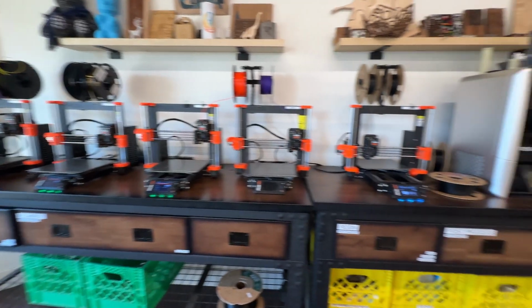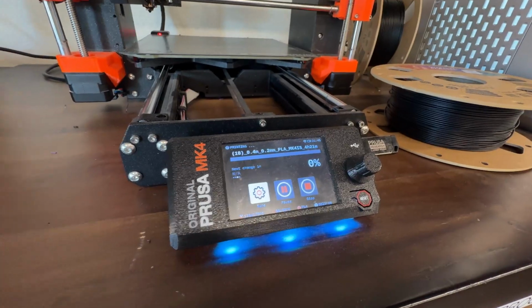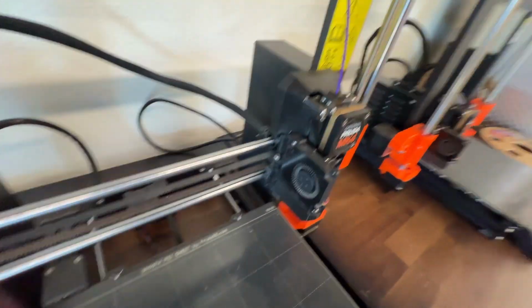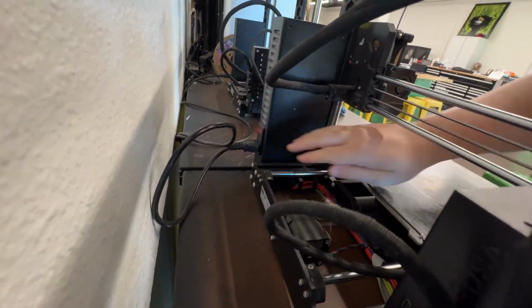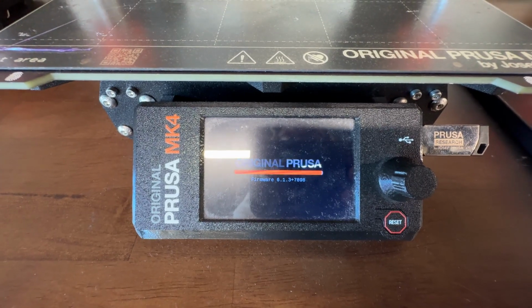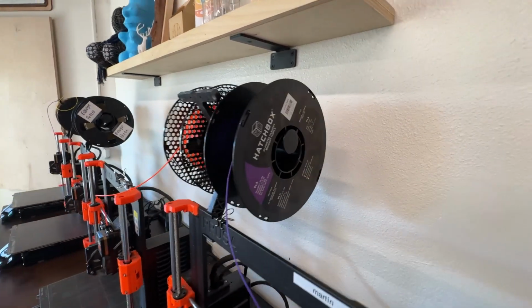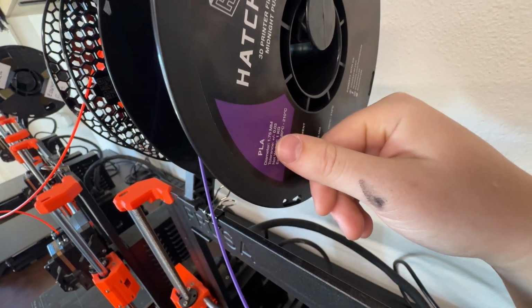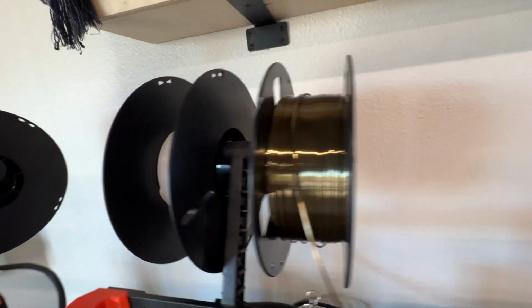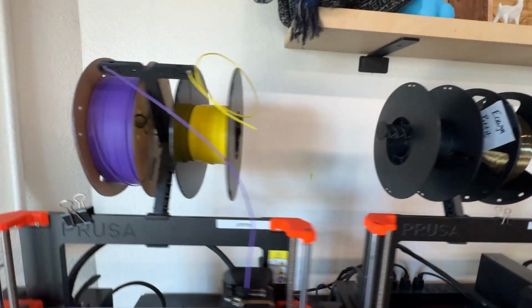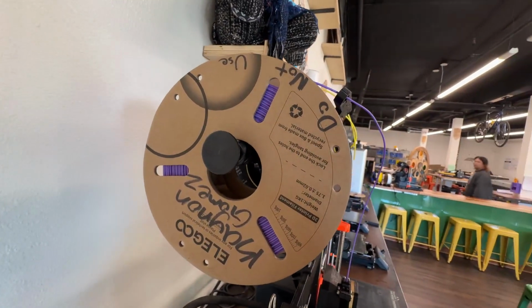Be careful. So I found one that isn't running a job. This other one over here is already running a job. It's already started something. So I'm gonna take the one that's off. I'm gonna reach around to get the power button back here. It's this red button. All right, screen's coming alive. I'm checking the filament up top to make sure it's free to use shop filament. It's PLA, this purple stuff. If the printer you want to use today already has someone's filament on it, go ahead and watch our short video below on how to change the filament out.